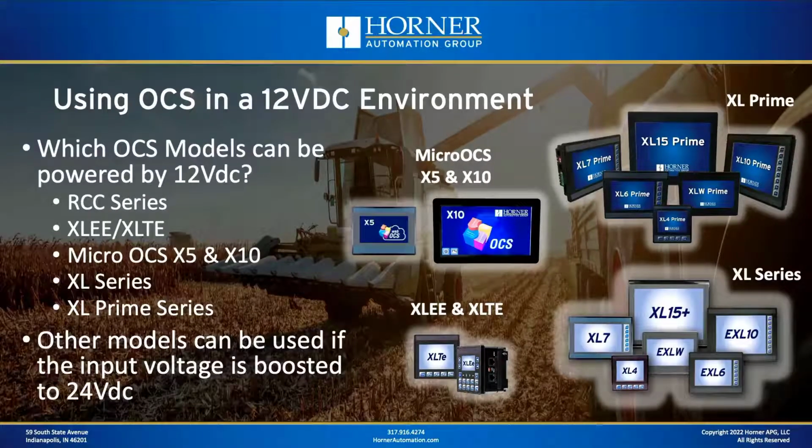Which OCS products are compatible with 12 volts DC? And basically, when we mean compatible, we mean two things. One is that they have a wide voltage range, typically 10 to 30 volts DC on the power supply side. And secondly, for any digital inputs that are part of the OCS, are those inputs compatible with 12 volt DC signals? In other words, are the turn-on thresholds such that you'll see an input turn on as appropriate with a 12 volt type input. So those are the two requirements that cause us to say, yes, these OCS are 12 volt compatible.